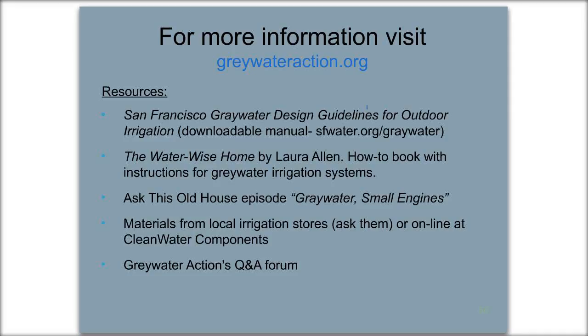Your septic system, if you're removing water from a septic system, what you're doing is extending the retention time in the system. All of the septic professionals I've spoken with about this, septic designers, wastewater engineers, have agreed that it's a good thing to expand retention time, and that removing graywater is actually going to help. It's not going to cause problems. So hopefully I addressed the question.